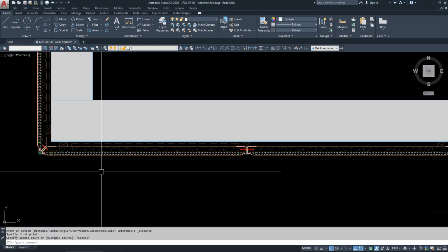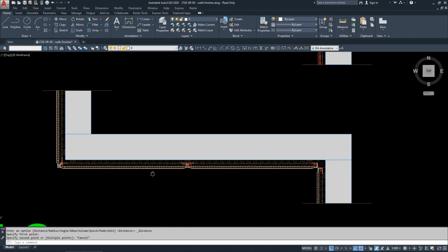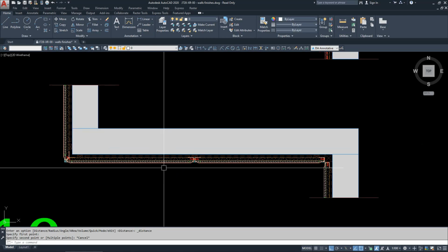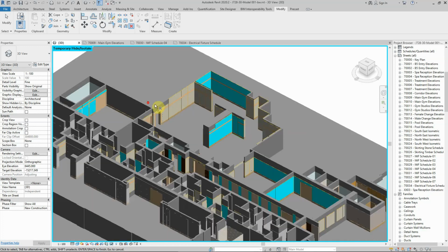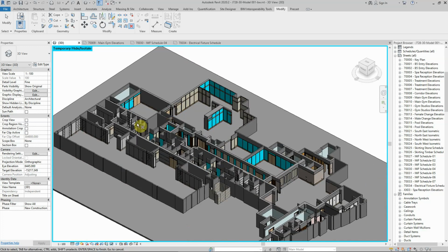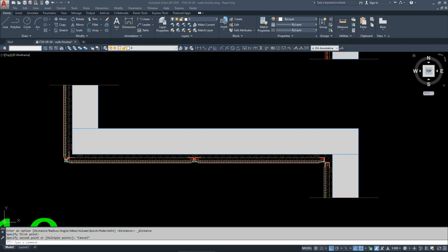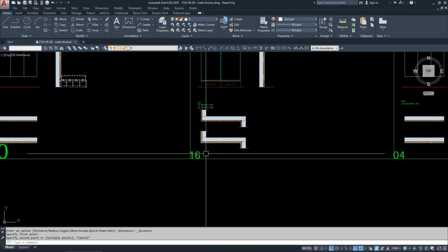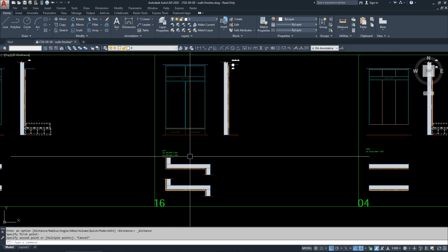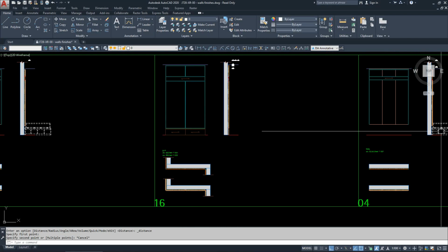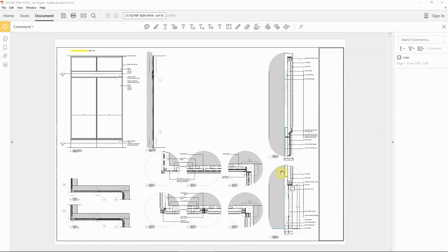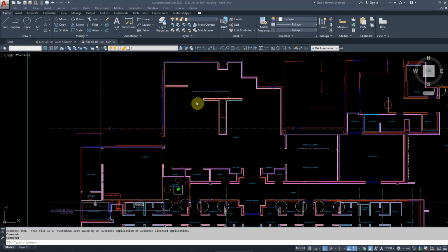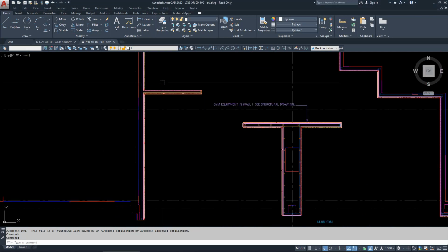So there's a to-and-fro process between AutoCAD, the 2D CAD, and the building information model, until you arrive at a stage where you have the full model with all the panels, the different types of panels laid out. You have detailed drawings of a particular panel type, the plans at different levels, elevation, and a section. You get a presentation drawing for approval of that particular wall type, and you get an entire plan of that space in 2D, which you can give to site managers.